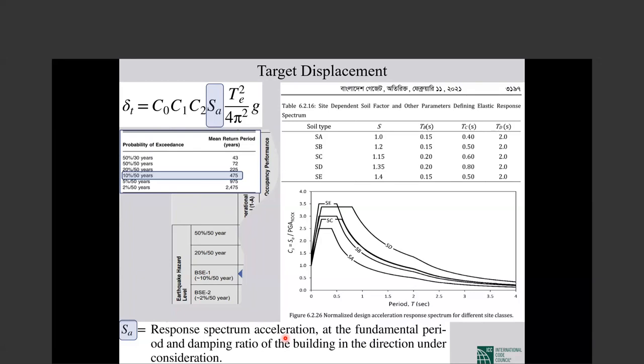Or use just the IBC curves, response spectrum curves for this level of earthquake, design level earthquake, it is good enough. So anyway, if 10% in 50 years, 475 years return period is selected, it is really just to use the IBC,